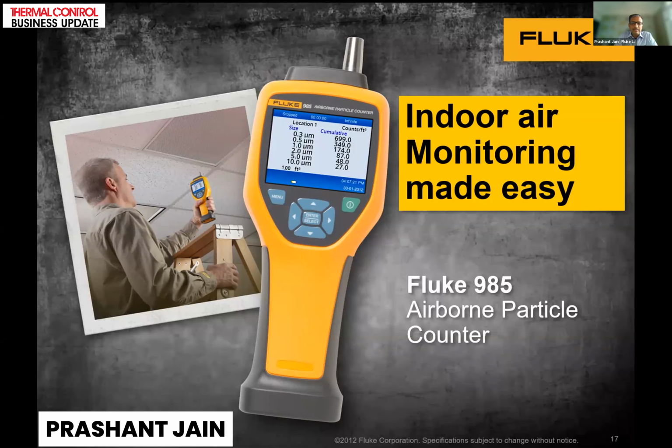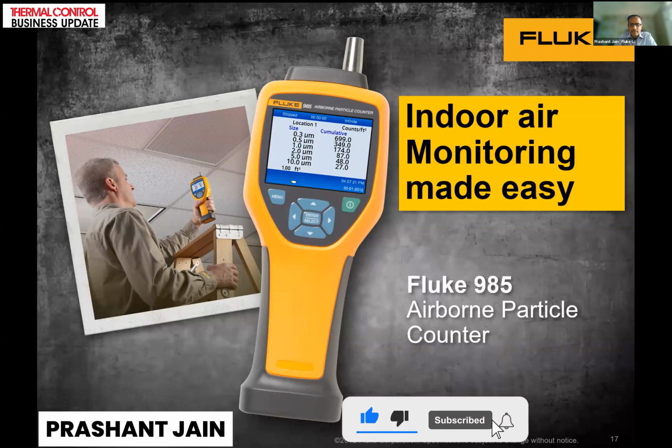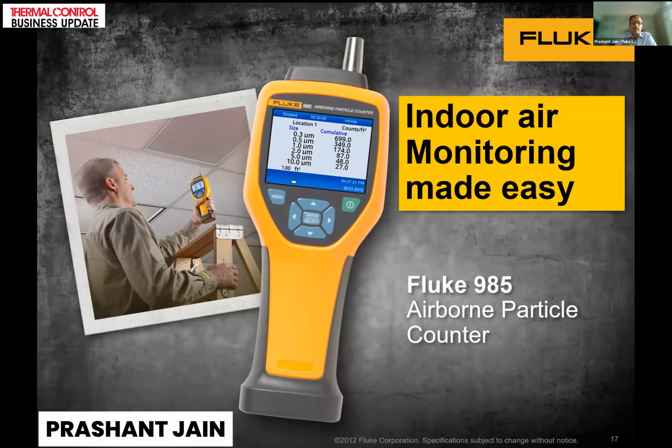Again, we discussed the fine particles. So here comes the MRI, or you can say the advanced tool for indoor air quality. This is a Fluke 985 airborne particle counter. It is a 6-channel particle counter which can measure right from 0.3 micrometer to 10 micrometer. And as Mr. Nitin has explained, PM 2.5 and PM 10 are somehow the most important or the most popular parameters which are generally talked about.